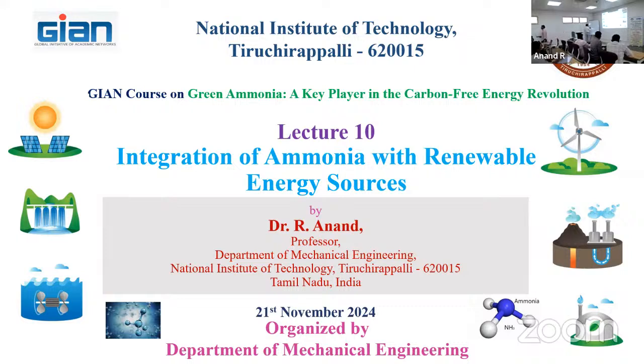Here, the organic Rankine cycle, ORC: in the organic Rankine cycle, the working fluid is not water. The working fluid is a low temperature fluid, we call it preferably a refrigerant. So we can use ammonia, whatever may be the refrigerant, okay? So chlorofluorocarbons, freons, right? Then the hydrocarbon refrigerants. We have to ensure that the boiling point of the working fluid we are going to use in an organic Rankine cycle is such that, even at near atmospheric temperature, it is able to produce the vapor.